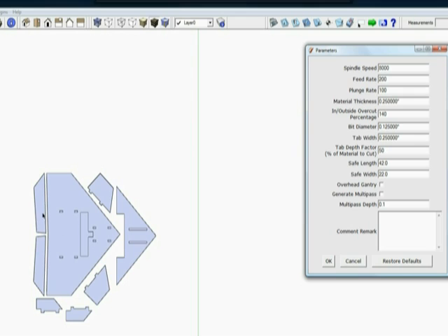Then when you do an inside cut, like when we notch out the inside of this prop slot, the bit would have to travel in the opposite direction, so that the material inside here was the scrap and had the fuzzy rough side, and again the finished part would have a smooth side.